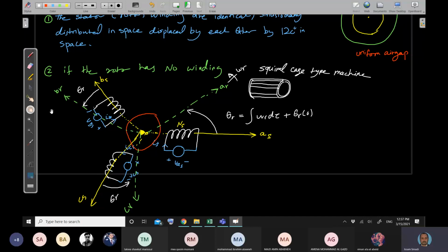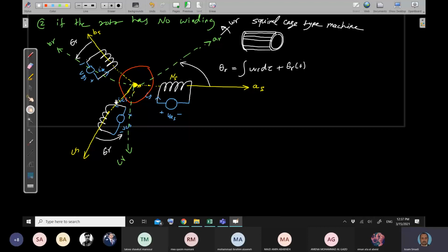Now, if I need to plot an equivalent circuit for the stator and the rotor, before that, let's plot the winding for the rotor. Now, if this one is squirrel cage, I will short those windings. Otherwise, I will connect a supply, similar to the stator case. Now, if I need to plot an equivalent circuit to represent the coils, I will use an RL circuit. So let's assume a Y connected circuit, and any winding consists of resistance and inductance.